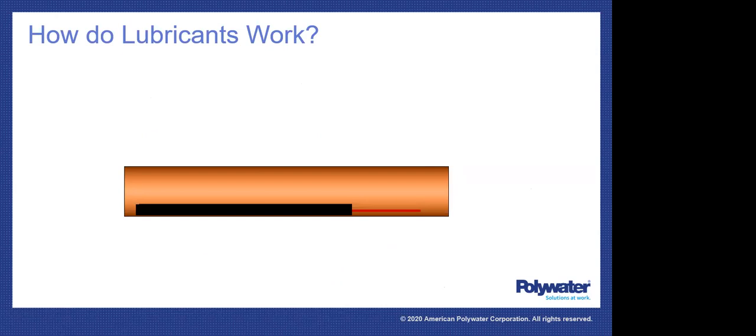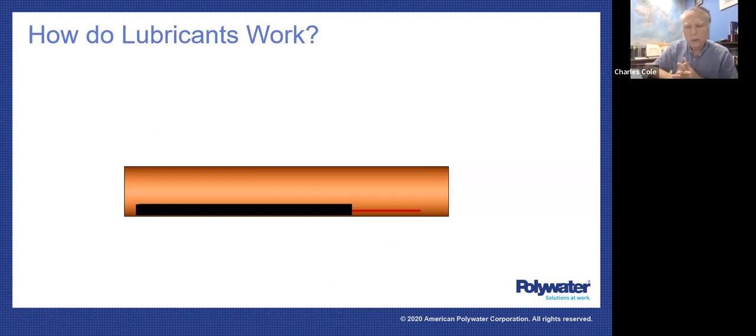So, we can look at how we can reduce the effects of friction, the mechanical forces that I talked about before. As I mentioned, the obstruction caused by ovalization or debris of an unproven duct is something that has to be taken care of before you actually start pulling cable into the duct.